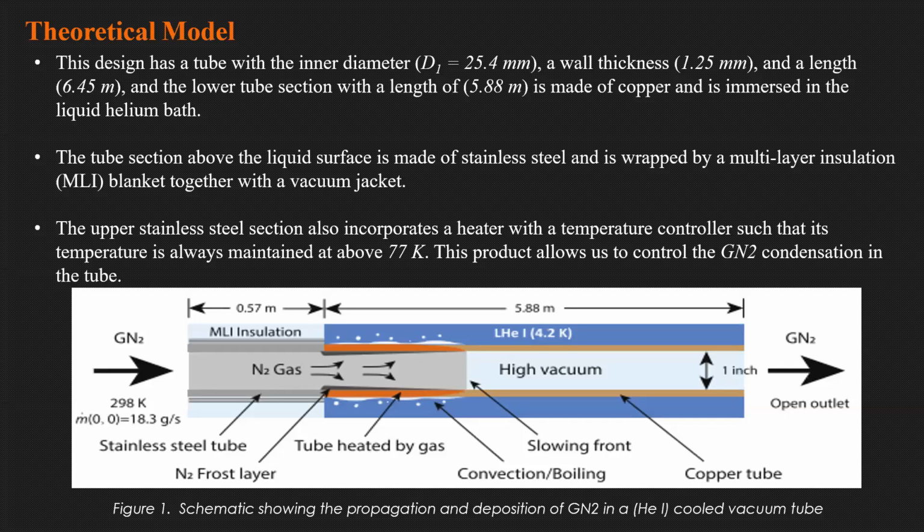In the theoretical model, this design has a tube with an inner diameter equal to 25.4 millimeter, wall thickness of 1.25 millimeter, and length equal to 6.45 meter. The lower tube section with the length of 5.88 meter is made of copper and is immersed in the liquid helium bath.